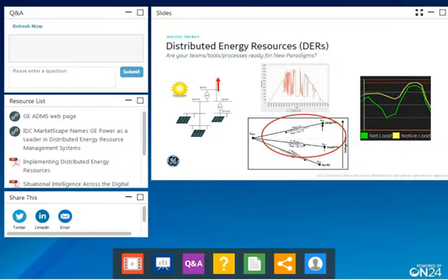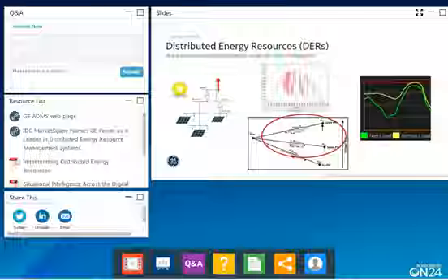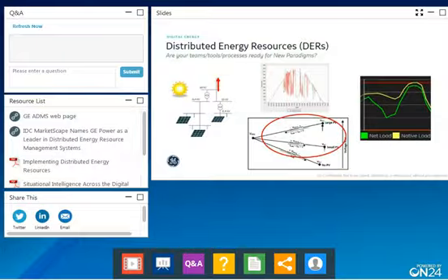On the right-hand side, you see net load and native load. What that means is that when you say the load is X on that particular feeder or substation, it doesn't mean a thing anymore. Are you talking about the native load, so the actual consumption, or are you talking about the net load, which is the native load minus what is already covered by distributed generation? You now need two terms. One is not enough. And all of this is further challenged with the intermittency, which you see at the top center here.